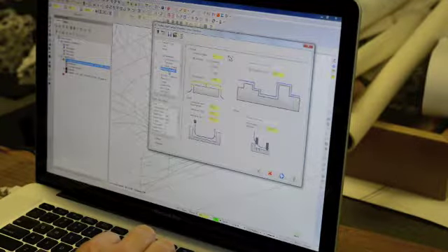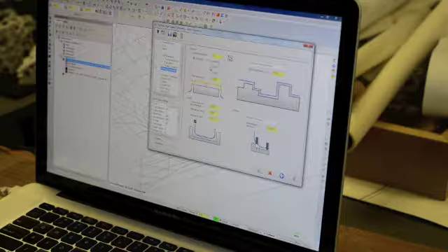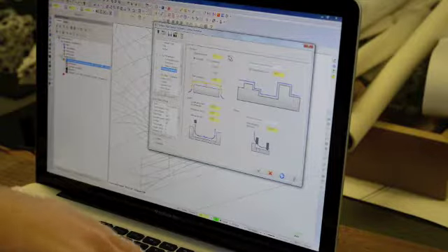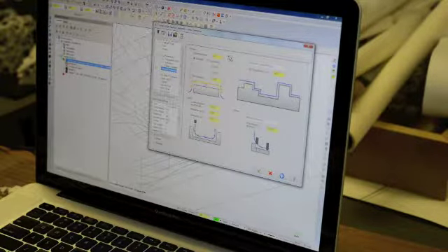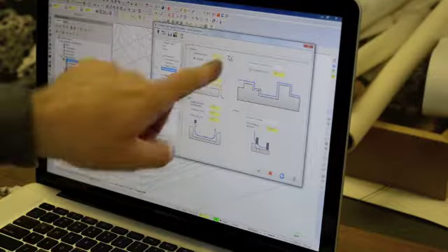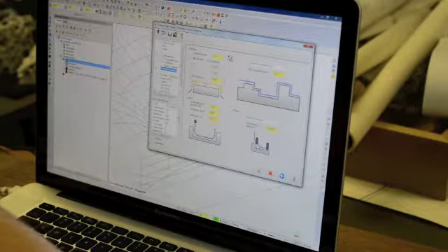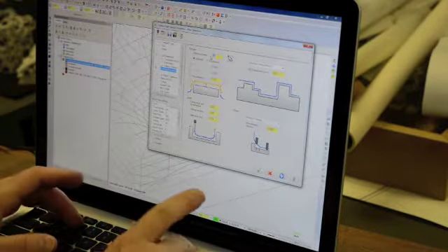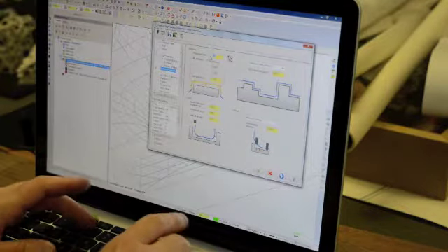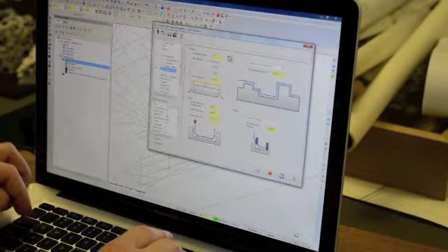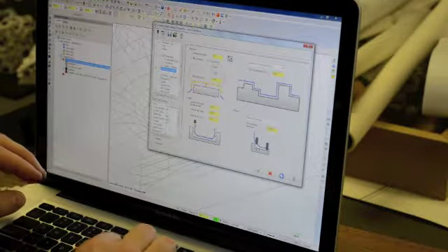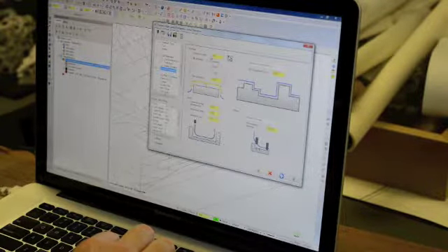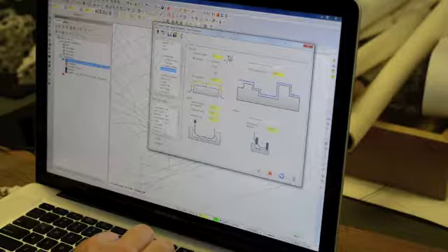Okay. Linking parameters. This is another important one too. So retract clearance plane. That's how far. So if this, for example, was our material thickness, if it was 2 inches and this thing is defaulted to 2, it's only going to retract to the top of this, and that will most likely cause a problem. So I always like to set this pretty high, so even here, I would do, say, 4 inches, to make sure that you clear your material completely, and you don't want to ruin your piece by this thing retracting only like 1.5 inches and ruining whatever your piece is.